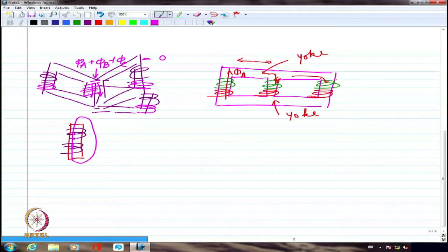Not really. I still have primary and secondary separately. I'm not having primary and secondary together. In an auto transformer, I don't have primary and secondary separately. So what I am trying to do is, this is the primary of A phase. This is the primary, secondary of A phase. So I have two distinct windings, and I have the opportunity to connect it in either star or delta as per my requirement. Most of the times, you might find that flexibility is there in certain specific applications.